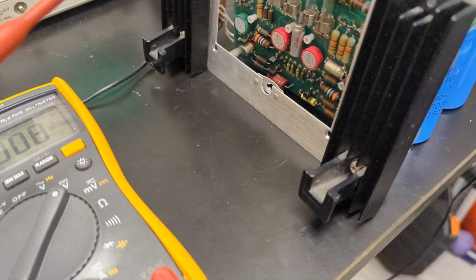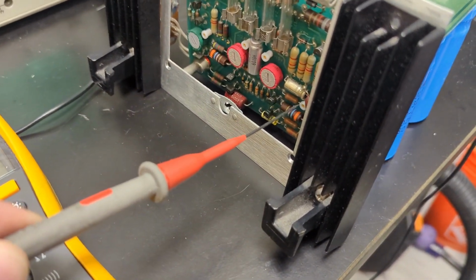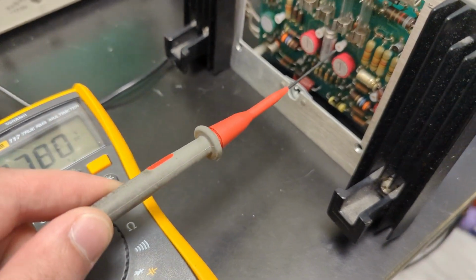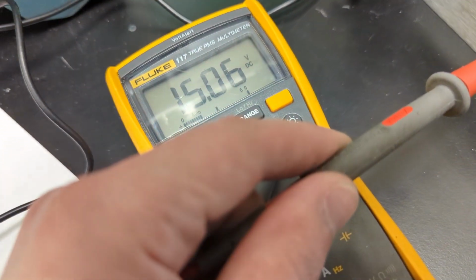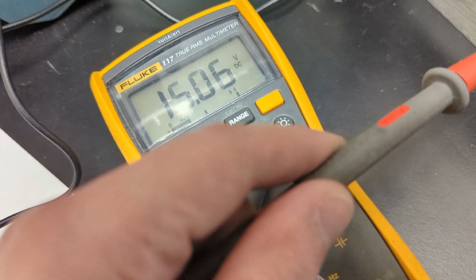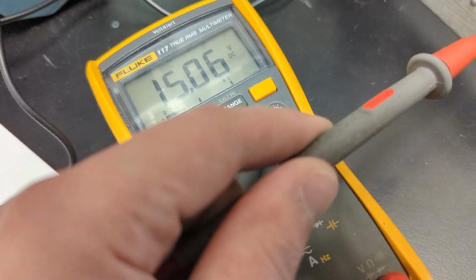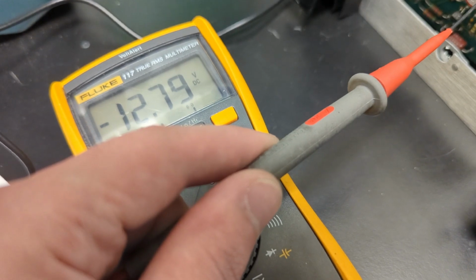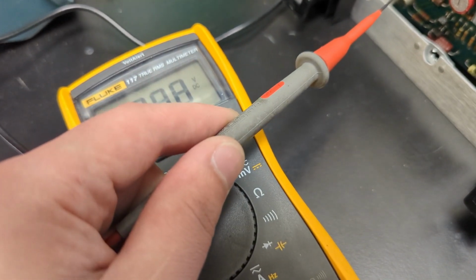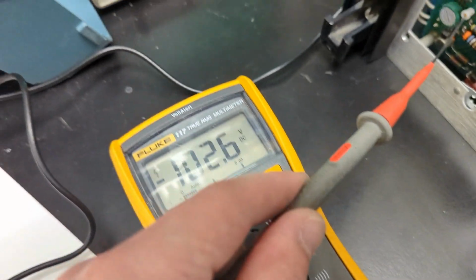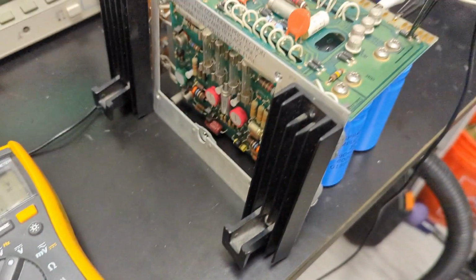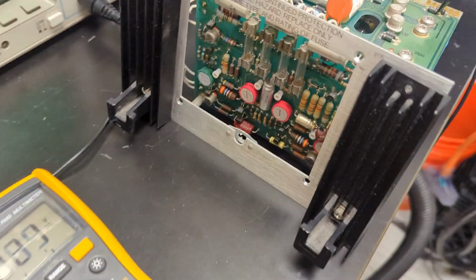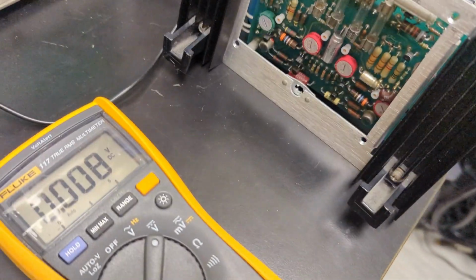Okay. So again, we're at 100 volts for the 100 volt rail. 15 for the 15 volt. Negative 12.7 for the negative 12.6. And 102 for the 100 volt. So, awesome. Which makes sense, just adjusting the 100 would bring the other ones back, but the other ones do have their own trim pots, which is pretty